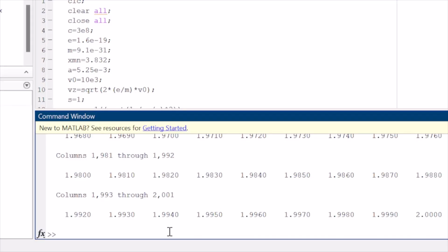Previously we had seen how to generate t. Now we have to generate the amplitude. So I will take the amplitude value as f underscore t, that is, function of t. The waveform has to be capital A into sine 2 into pi f into t. Pi is a constant which is already available in MATLAB, so we do not explicitly declare it.